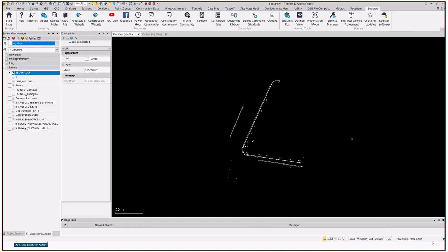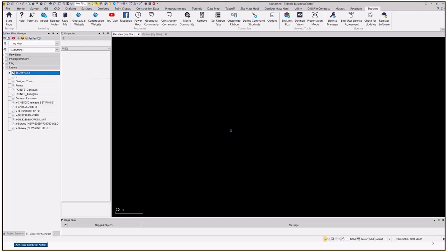So I'm just going to select some more, a whole bunch of it like that, Control L, it throws it into our Survey Unknown. I'll just do the rest of it now. Okay, and that gets rid of our default. Anything that's in default, there's nothing in there anymore. I don't have to worry about that. That's just another layer that can go bye-bye.